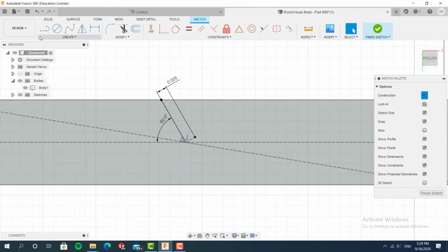So first, define the middle. Draw a line that is going to be 60 degrees from one of the sides of your extrusion, and then just start drawing out the triangles. The only number that you need to define here is basically how thick you want the sides of the triangle to be. In the case here, I put a side as 5 millimeter because it needs to hold quite a bit of load.